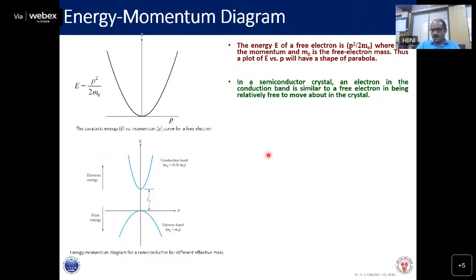Since in the conduction band, all the energy levels above, Ec plus e delta V, are also available and free, meaning no other electron is occupying them, you can give any small amount of energy and this electron will be able to accept it.